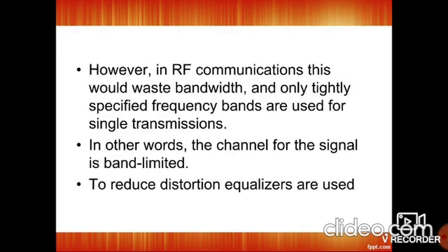The signal x of t is simply the data transmission system given by input, transmitter, channel, and finally receiver. The transmitter has data encoding followed by a transmitter filter and channel, and the receiver has a receiver filter followed by a decision device.